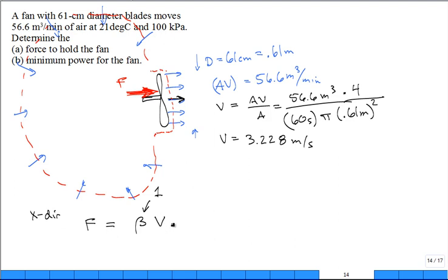and then the mass flow rate of the air, exiting in the positive x direction. So there's negligible input, and it all exits with that momentum flow rate. Get rid of the beta; beta is 1. If I want to know the force, I know the V already. I just need the mass flow rate. How do I calculate the mass flow rate?